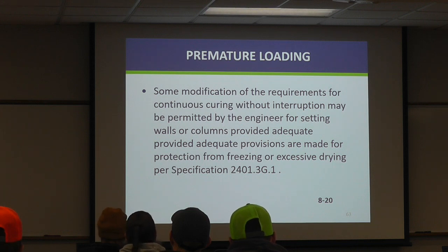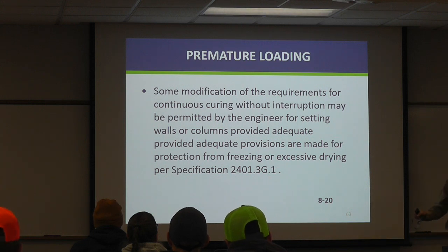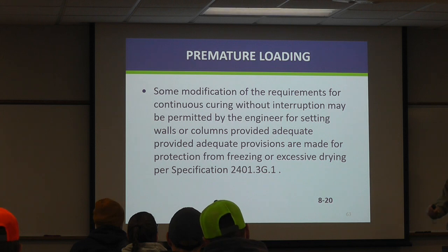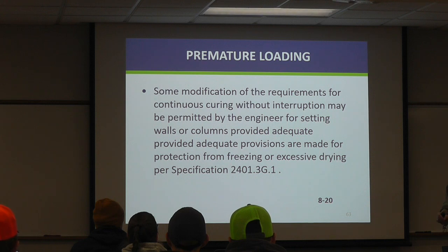Over time, there used to be a lot of heated discussions between contractors and inspectors, engineers, over when can we start going up. We've cast this footing, we've cured it for 2 days, and we want to start tying rebar for the pier column. And some inspectors would say, no, you need 72 hours, and others would say, okay, you can disturb it.